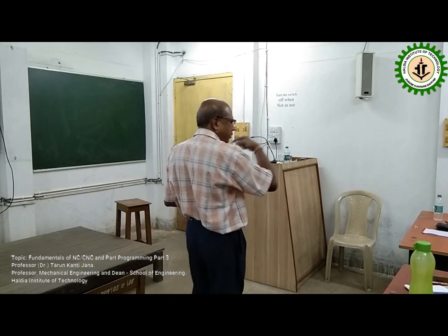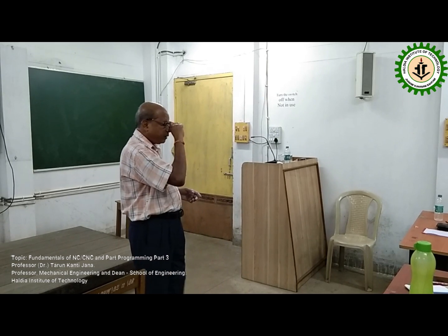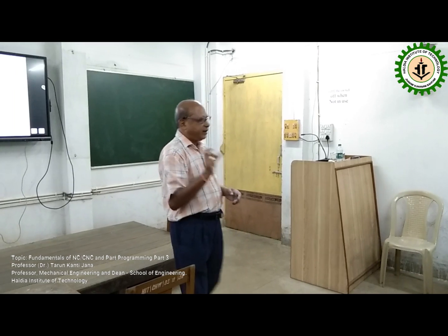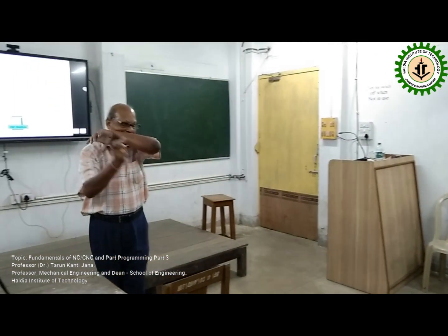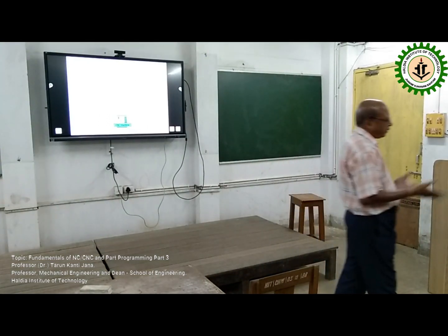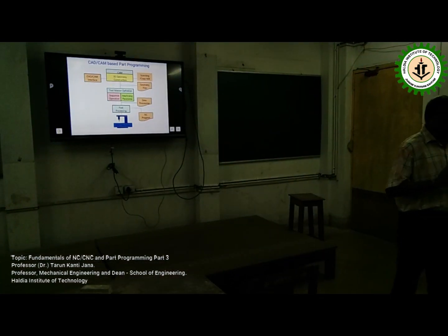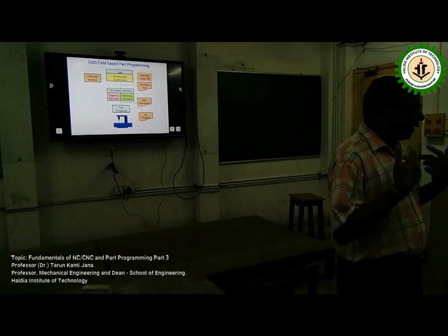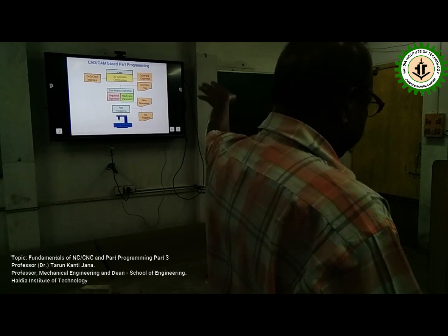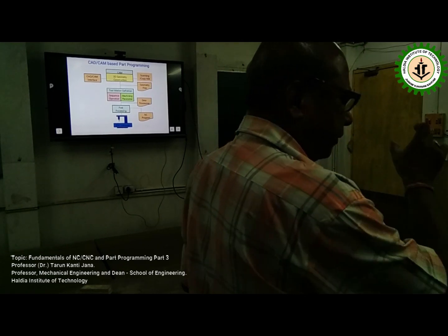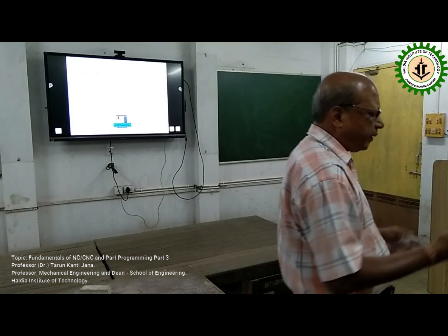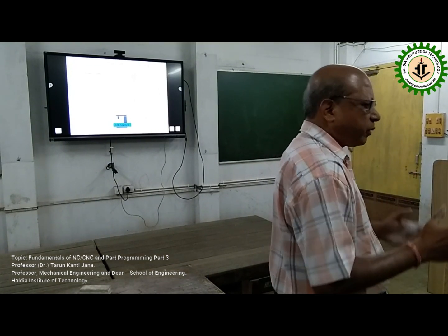If your objective is to go point to point, then the corresponding G code will be different, since each movement has its own unique address code. Those codes we have to remember slowly; even mechanical people automatically remember some codes. Specific things are supposed to appear in a specific canned cycle. If you explore, a lot of address parameters will be coming, which we call R parameter, P parameter.